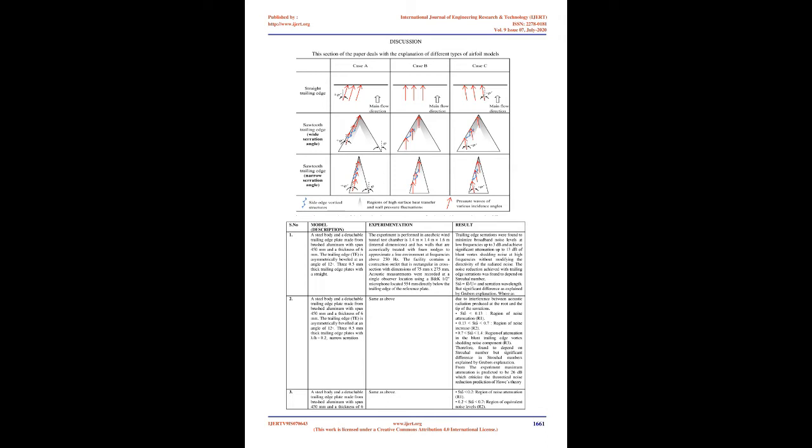Measurements were carried out at zero angle of attack for 3 different free stream velocities, U = 10, 15, and 20 m/s, corresponding to chord Reynolds numbers of 3.87 × 10^5, 5.8 × 10^5, and 7.73 × 10^5 respectively, as the turbulent flow field around the trailing edge is the source of trailing edge noise. Velocity measurements near the trailing edge of the flat plate with and without surface treatments, baseline, are studied to gain insight into the mechanism by which fences affect flow structure.